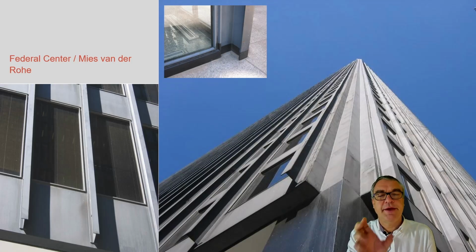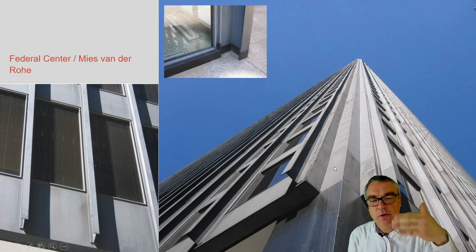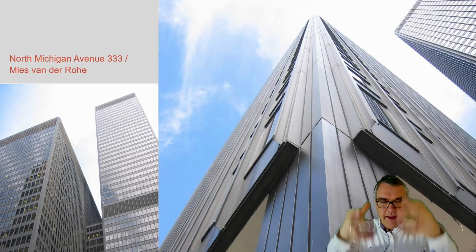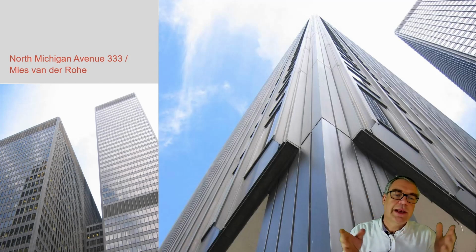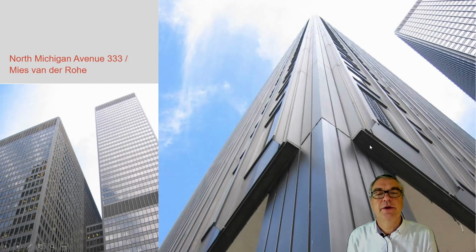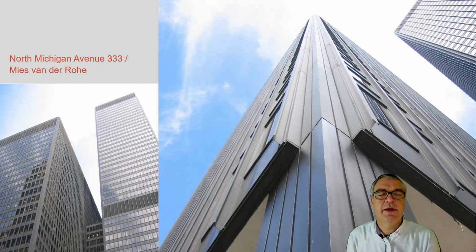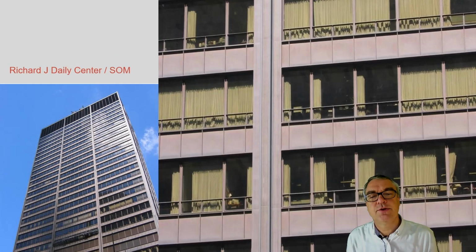Another experience which we can identify clearly here is that this is still solid steel as a system, so a solid steel structure. And again, if this gets cold, it gets cold at the inside as well. They learned this problem and started insulating it. So the main structure is now insulated with an additional layer, still appearing as the Mies corner, which we see here, this outline, and still the same type of facade being used. Aesthetically, with this I-section, the slenderness of the I-section expresses itself to us. It's actually technically not giving a lot of additional functionality.